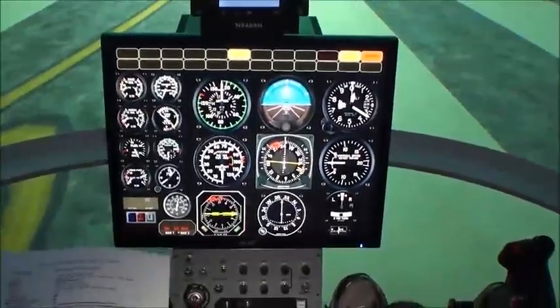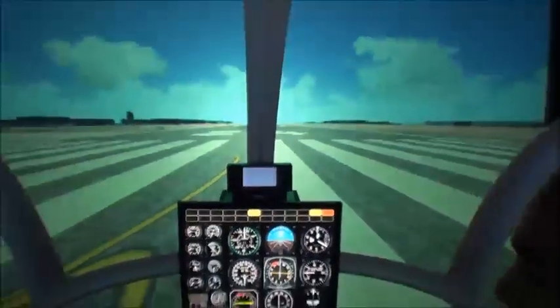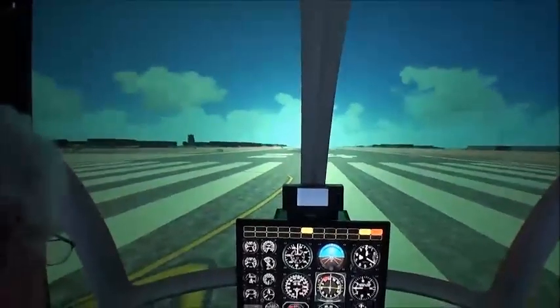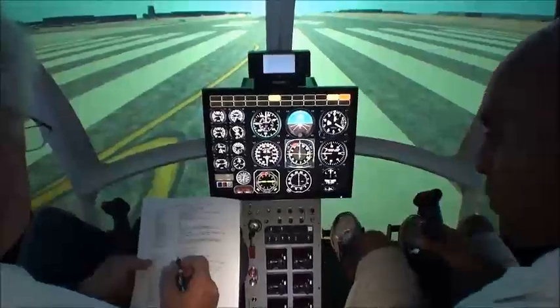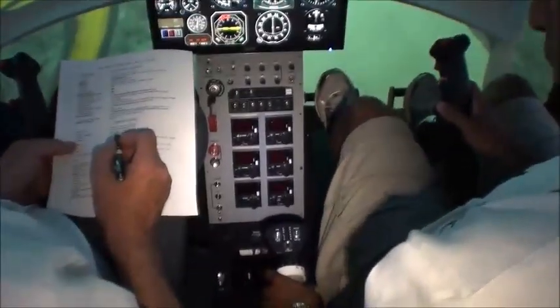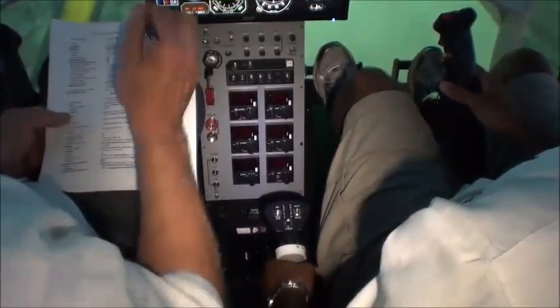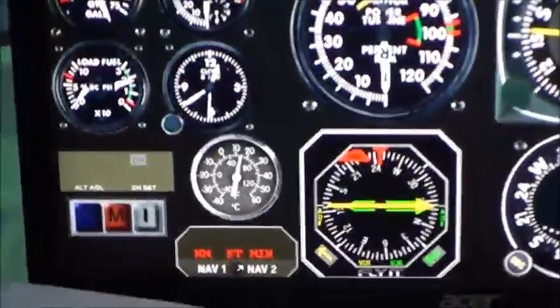Okay, rotor blades untied. Got 90, visual check. 90 and 70 untied, check. 9270, okay. Area clear. Clear on my side. Okay, collective, friction on, and pedals neutral. Check. Throttle fully closed. Fully closed, check. Okay, we're going to start timing our start. Watching the clock here. Okay, so go ahead and engage the starter.